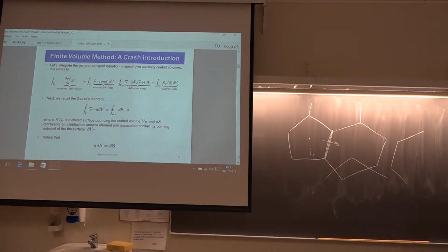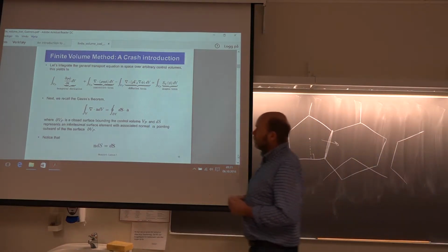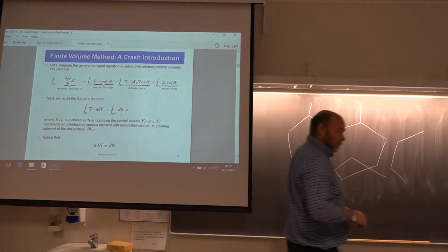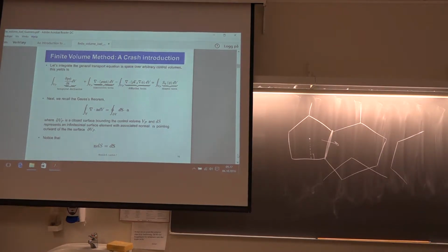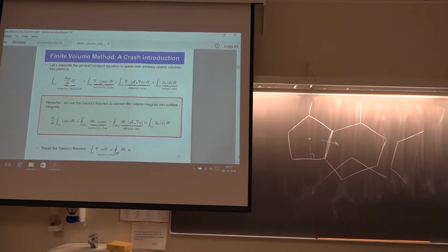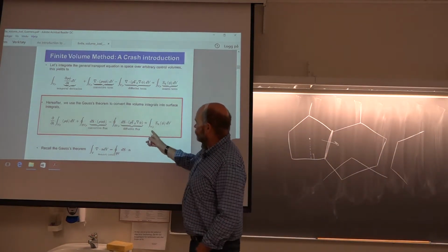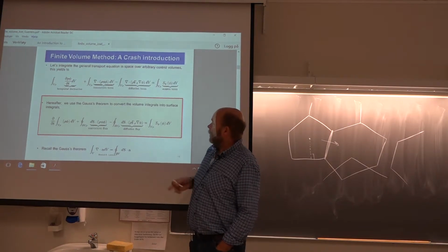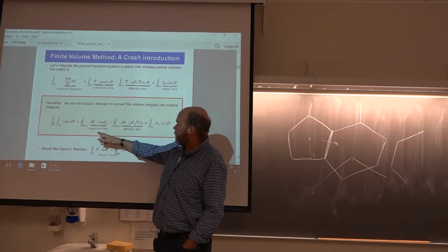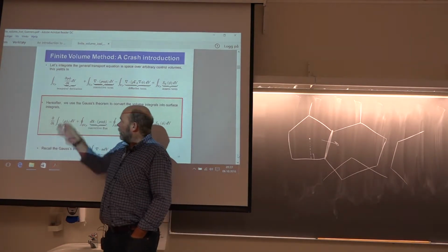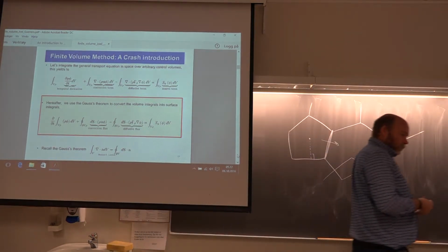Then we can jump from our volume integral and use the divergence theorem and rewrite it as surface integrals. This is done with all terms except the source term. That one will still be a volume integral, but the diffusion and convective flux terms will now be surface integrals. The time derivative we haven't really discussed yet, so we will wait a little with that one.